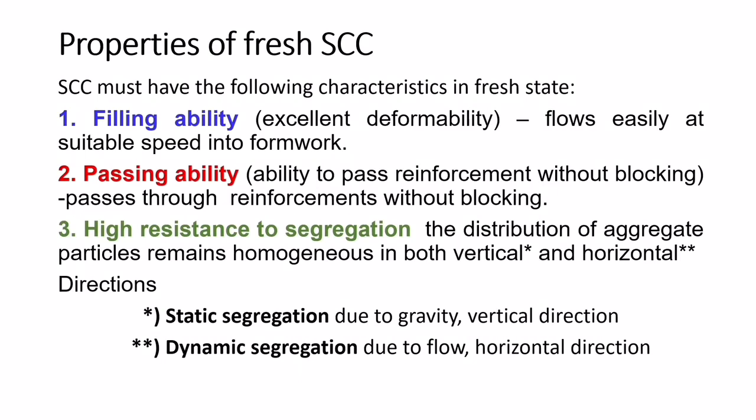Properties of fresh self-compacting concrete. Self-compacting concrete must have three characteristics in a fresh state. The first one is filling ability: it flows easily at suitable speed into the formwork. Passing ability: the ability to pass through reinforcement without blocking.